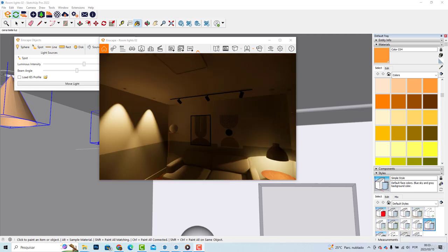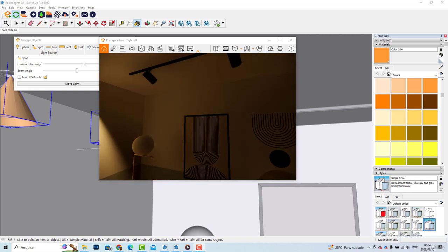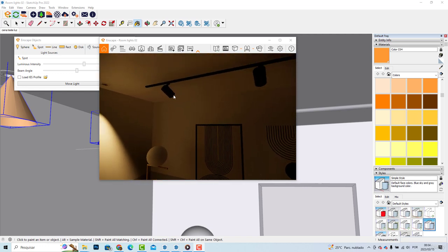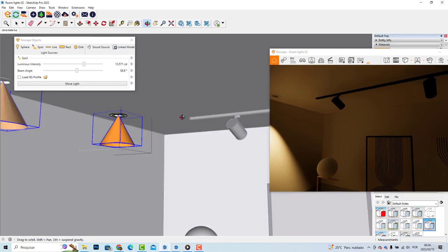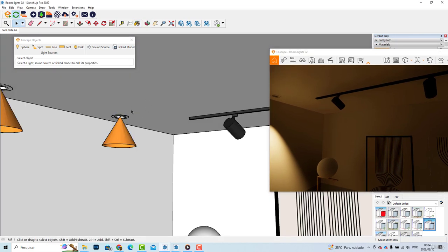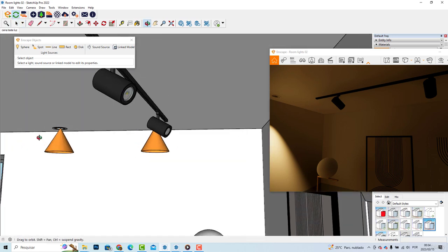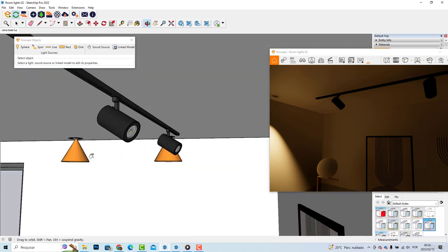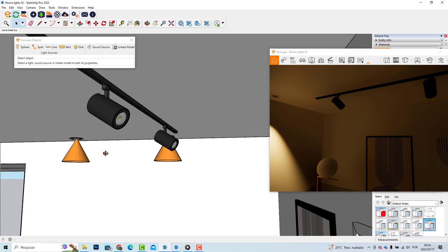Okay, so I would like to go on and place some more spotlights in our room, and maybe I can place them here in this track lighting fixture. And here it would be important to once again use the line as a reference to place the lights. So I will try to find a good angle. I can hit my ESC key to leave our former components, and now I can orbit my view. I think somewhere here it's quite okay. And once again, I will create a line.